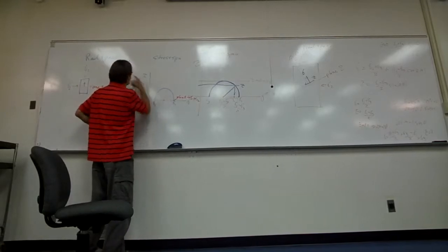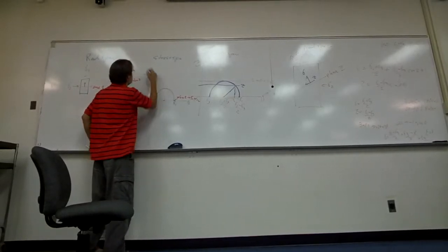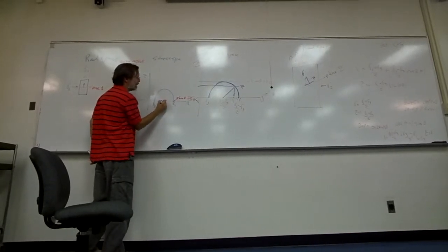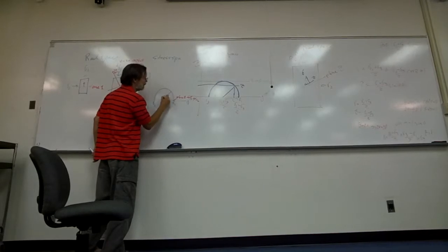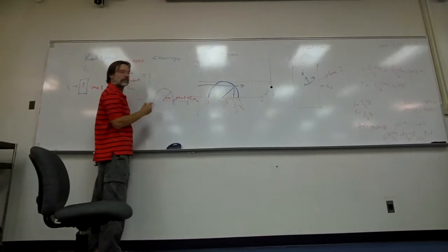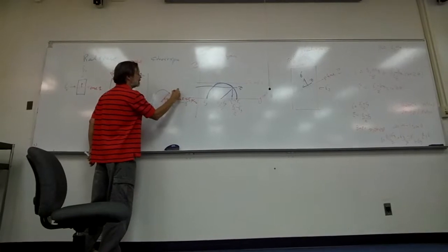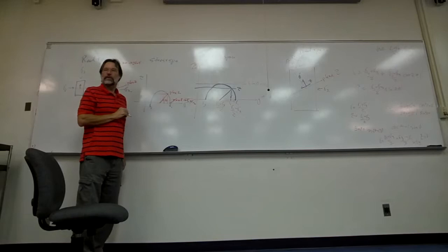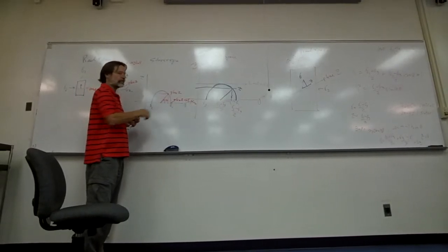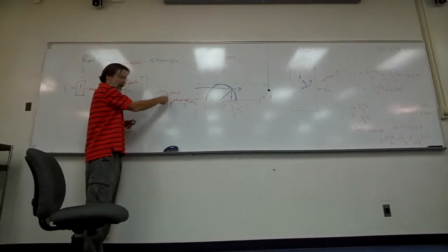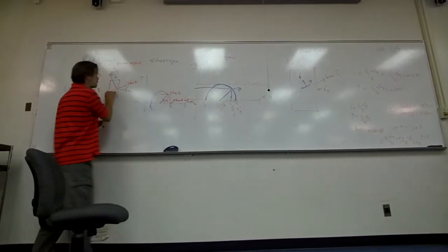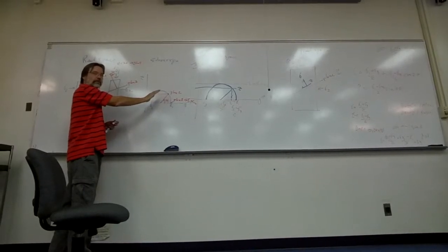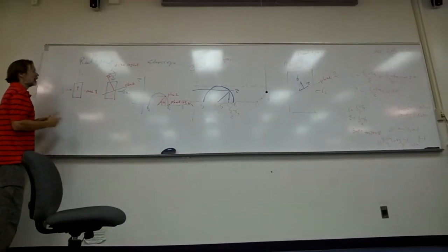I count in this position, 2 theta is 40. I just take my protractor out. There's 40 degrees. That's plane 2. Sigma and tau for that plane are resolved in those values. It has high normal stress because it's close to this plane, but the shear stress is increasing, right? Fair enough?